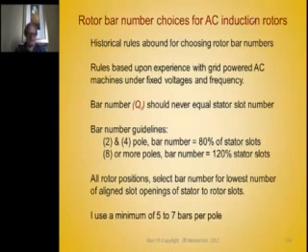So you have a lot of bars to provide the current flow that produces each pole, and different motor design experts down through the years have come up with sets of rules on how to pick the number of bars with respect to the number of stator slots. But most of these rules were determined from experience of trying to start induction motors at a fixed frequency and voltage off the grid. That's where all those rules came from.